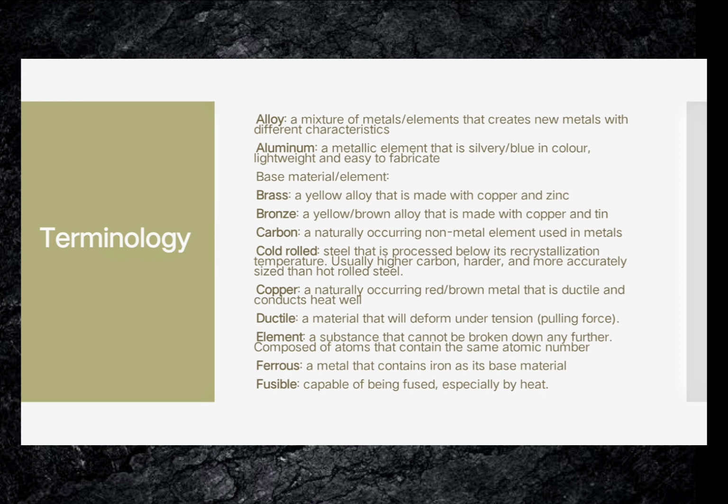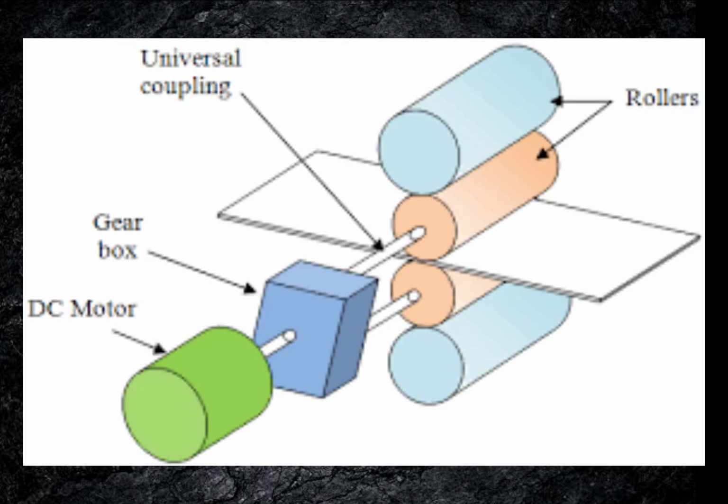Cold rolled steel is essentially hot rolled steel that has been processed further. Once hot rolled steel is cold, it is then re-rolled at room temperature to achieve more exact dimension and better surface qualities. Other cold finishing processes include turning, grinding, and polishing, each of which is used to modify existing hot roll stock into more refined products. Due to additional processing for cold finished products, they come at higher prices.